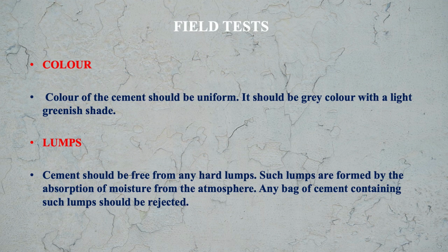First is color. For good quality of cement, the color of the cement should be uniform, the same color throughout the bag. It should be grey color with a light greenish shade. Fresh cement or good quality cement should have a light greenish shade with grey color.